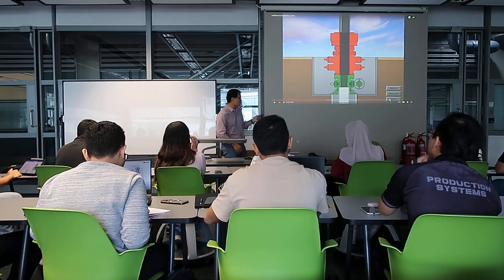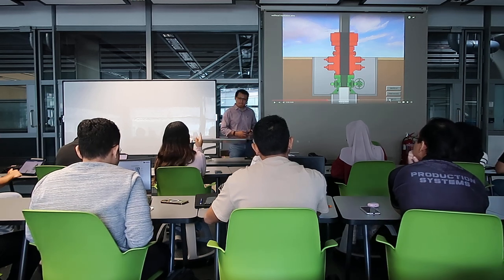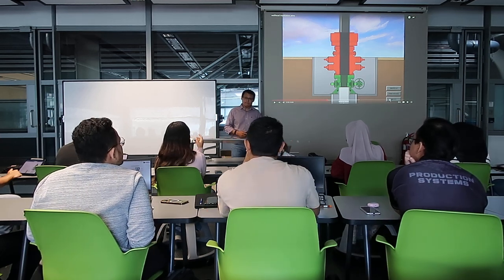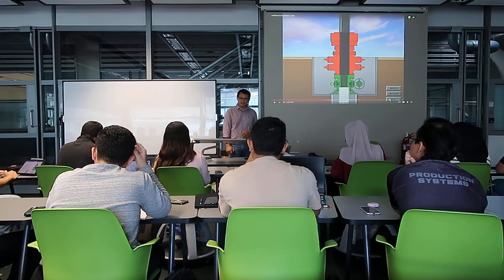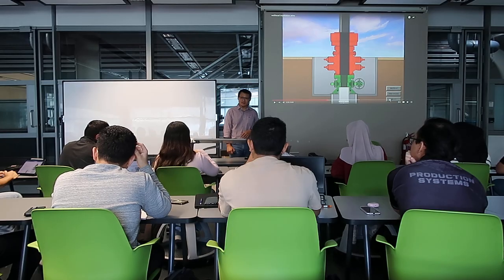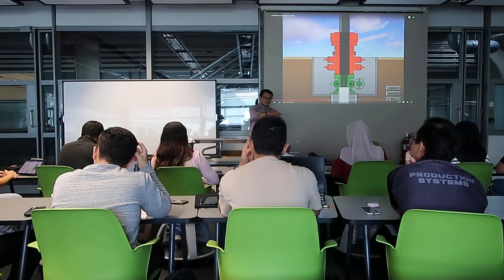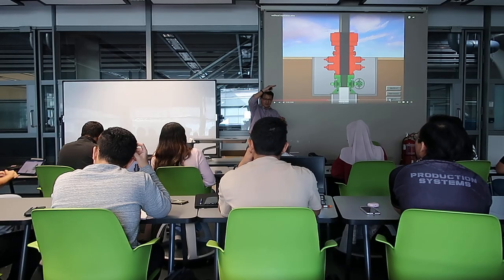That's how we do the BOP test. But for the full test of the BOP, you have to do it with the API certificate because, like we are saying, every time you test the BOP it's not connected to the well. So you put on the test stump, whatever the RAM above is tested good.